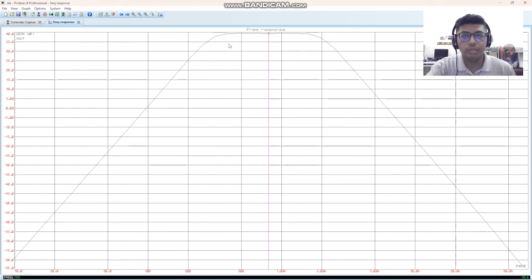So what we have to do here is locate where the low pass frequency and the high pass frequency are. For 39.4, we must subtract 3 decibels from it so that we get both low pass and high pass. So 39.4 subtract 3, we took out 3 from it, we got 36.4, right? So we move our cursor to 36.4, as you can see on the bottom right of the screen, and at the bottom left of the screen we get 299 Hz, which is good because we intend to get 300 Hz on the low pass frequency.